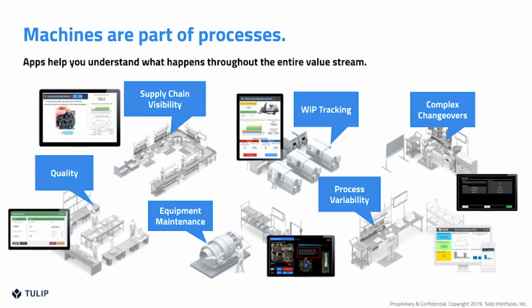Well, usually one of the big first ones is uptime and downtime. That's very basic machine monitoring. It's one of those things that we like to call low-hanging fruit. The key performance indicator that we add on to that, though, is downtime reason codes. So when the mill is down for X amount of seconds, or if it's down for more than 2 minutes, whatever your load time is for the next part, it would bring up a reason code screen, and the operator then interacts with the application, selects the reason code, and then that gets stored in the data.